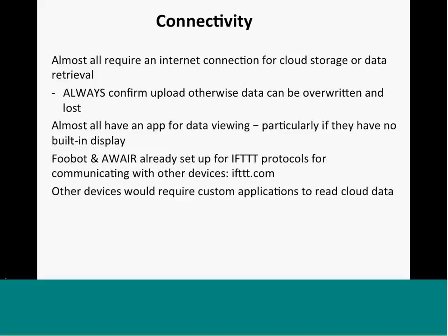And a couple of these devices, the Foobot and the Aware, they're all set up for something called "if this then that", which are protocols for communicating with other devices. So they're a fair way down the path of having the capability built in that they would have a control signal that you could detect for turning on and off ventilation or filtration systems. For the other devices, so long as you can have something that will actually read the data in the cloud, you could write some sort of custom application that would allow you access to the data for real-time control.